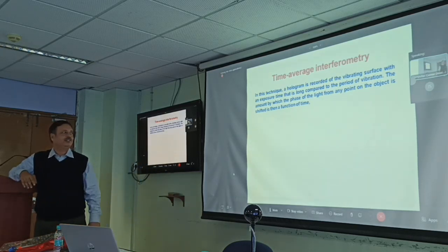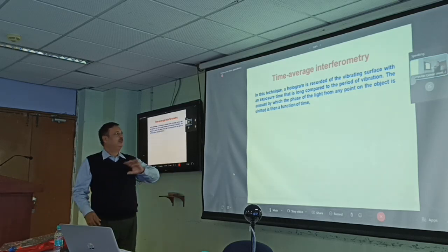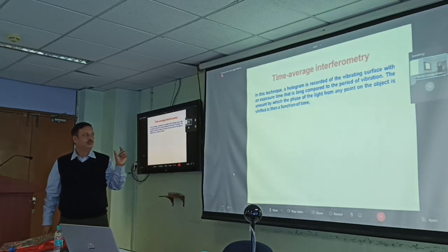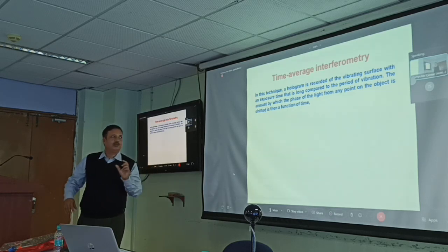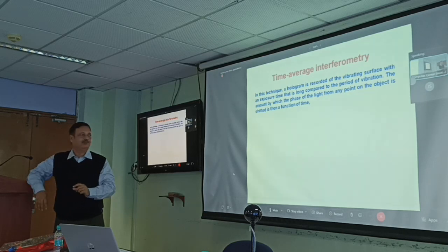This I showed you that picture again. So here the important point is that the exposure time should be long compared to the period of vibration. If it is not longer than the period of vibration, then you won't be able to record any information. So this is very important here.